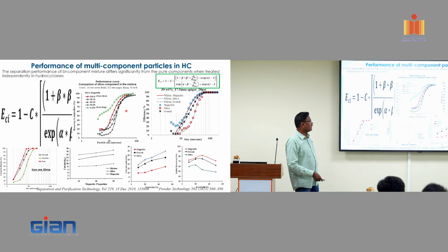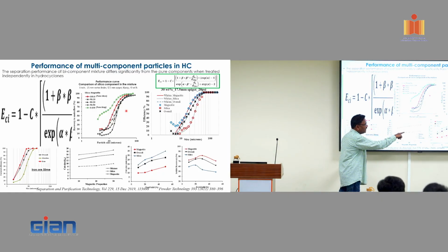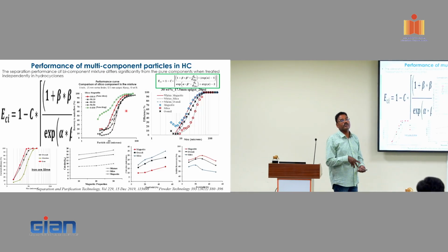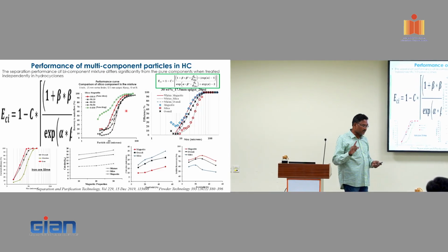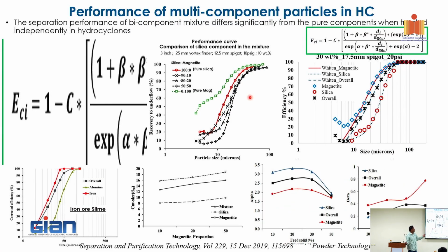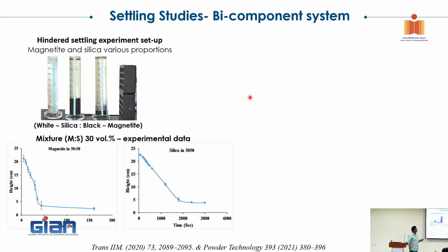No, your solids recovery to the underflow, you see, it actually decreases for the silica component, the lighter density, a lot more compared to what happens in the mixture. So that means there is a lot of interference by the heavier particle on the lighter component. Now, I think the efficiency and all of this we can look at, but we can also find these things in the published literature.